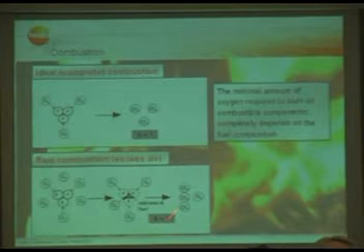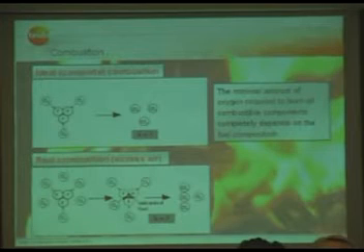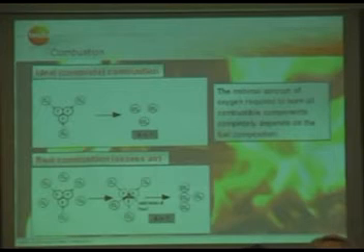This is when we are talking about excess air, or when lambda is greater than 1. Because this is taking place in the real world, you have to be careful that the amount of air you provide for the combustion is just enough to burn the fuel completely, because if you provide too much air, you have a higher flue gas loss, and therefore you lose a lot of energy, which is not really necessary.